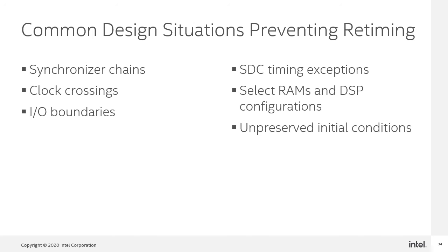These and other retiming restrictions, as well as potential solutions, are covered in much more detail in the Intel Stratix 10 FPGA High Performance Design Handbook. You can increase your design performance by eliminating the retiming restrictions, or since some of these restrictions cannot obviously be removed from your design, by using these points in your design as targets for adding extra pipeline stages to allow for more retiming there. This technique is covered in more detail in the follow-up training on hyper-pipelining.